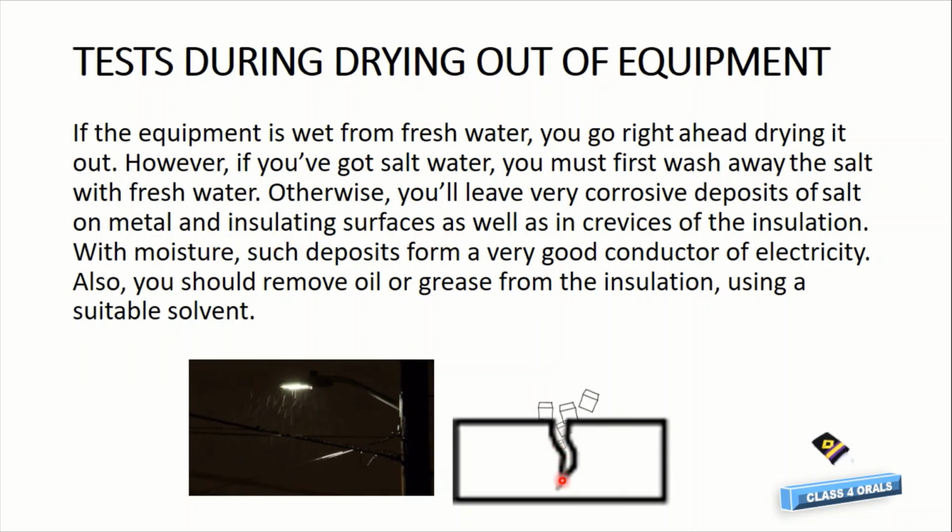Crevices may form in the insulation, and the salt deposit can cause the insulation to go bad, because such deposits form a good conductor of electricity. So we should remove oil and grease from the insulation using a suitable solvent.